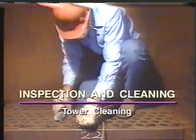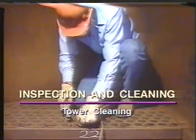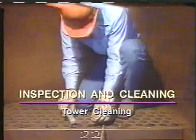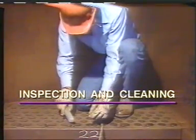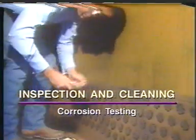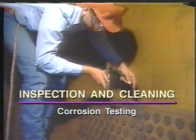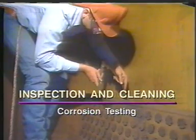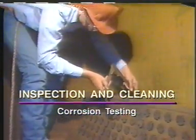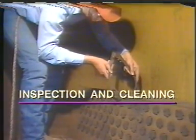Cleaning of the tower should be thorough and complete. Even after purging and water flooding, there are usually some stubborn deposits that remain in the column. These deposits are removed with special solvents or by manual scraping. After the tower has been thoroughly cleaned, it must be carefully checked for corrosion. We do this to make sure that all equipment is still strong enough for future use. A corrosion inspection is usually made by measuring and recording the thickness of various metal parts inside the column.